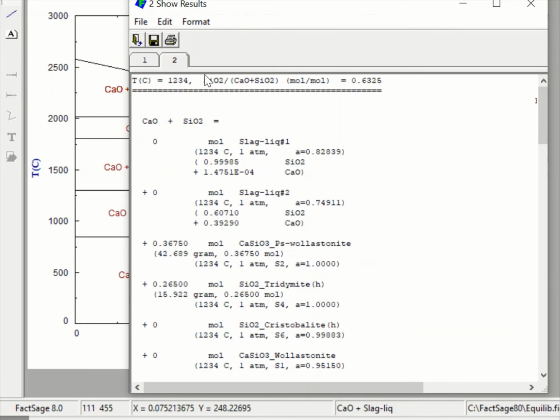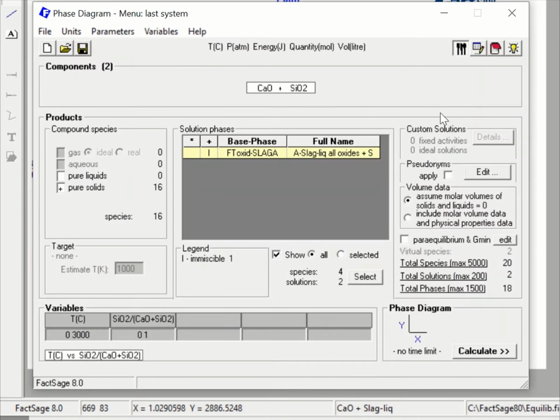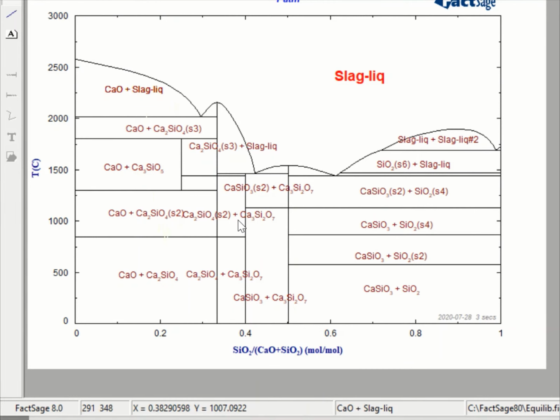So sometimes, binary system is easy, and even ternary system is reasonably easy to understand how much phase, according to the binary lever rule or ternary lever rule. You can more or less estimate what's the amount of each phase at the given composition from the phase diagram. But when you go to the quaternary system, theoretically, it's very, very difficult to know how much amount of each phase is existing in the quaternary phase diagram, because it is not on the one plane.